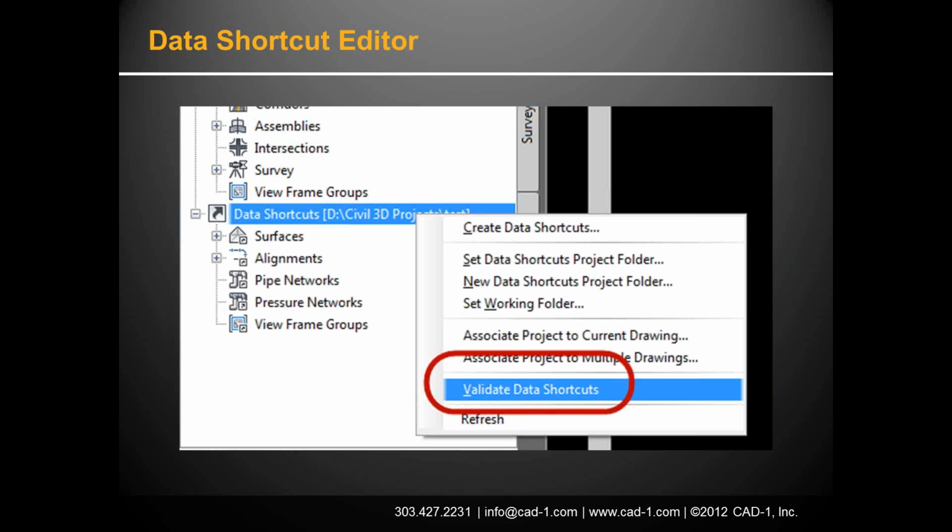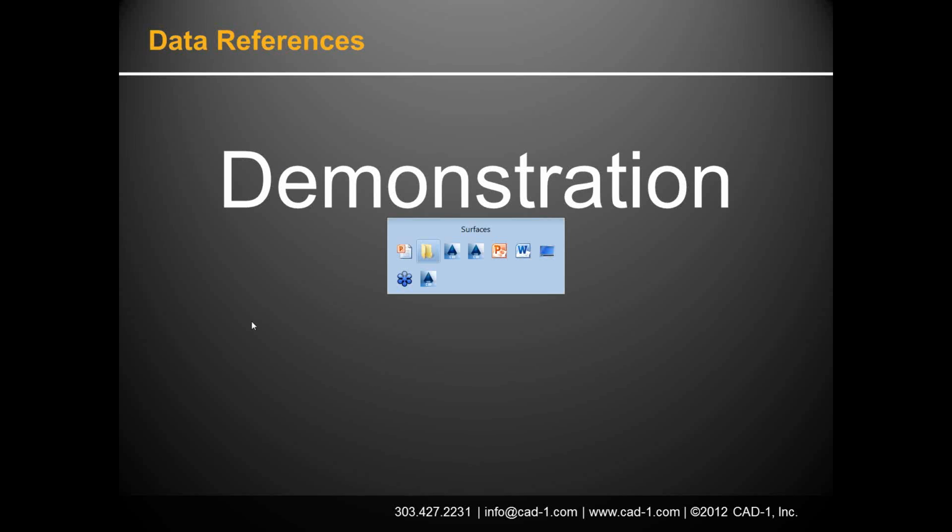After you've edited the data shortcuts using that, you'll want to validate the data shortcuts. And when you validate the shortcuts, everything magically gets fixed. So let me go ahead and demonstrate that here.